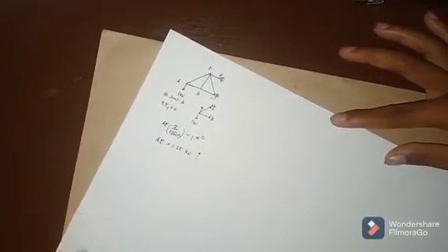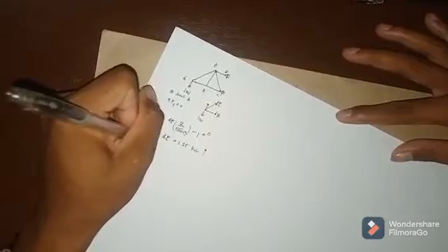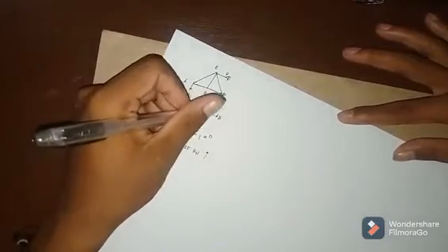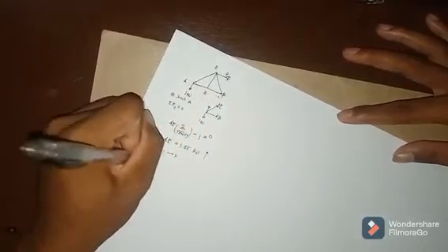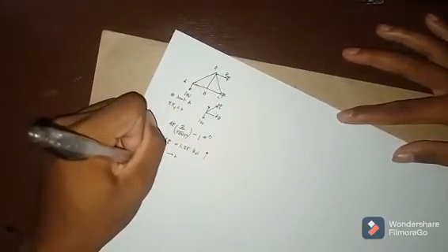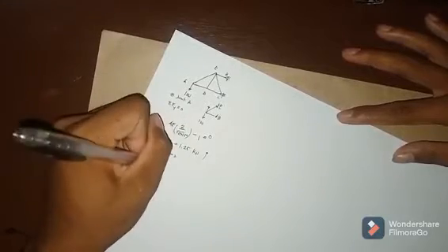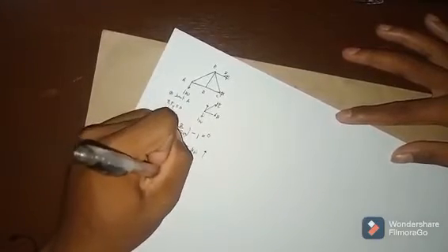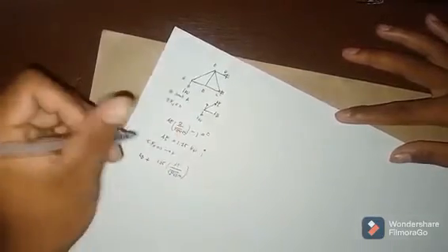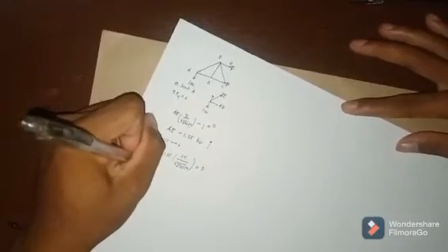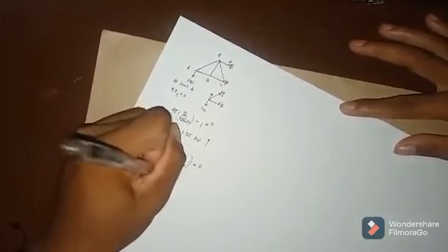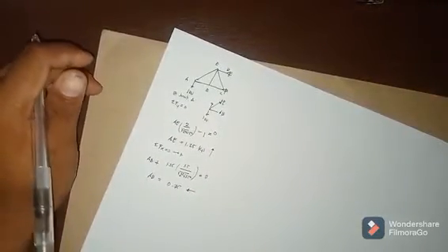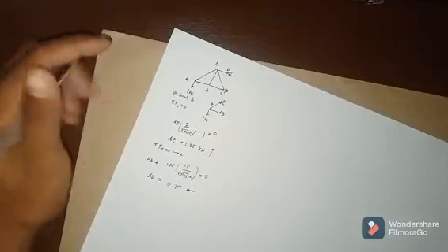So solving for the horizontal, summation of forces horizontal is equals to 0 and also that positive. So we can say that our AB is positive, then plus our AE which is 1.25 times the cosine which is 1.5 over square root of 2 squared plus 1.5 squared equals 0. So we can get 0.75 to the left kilonewton. So this is for our joint A.